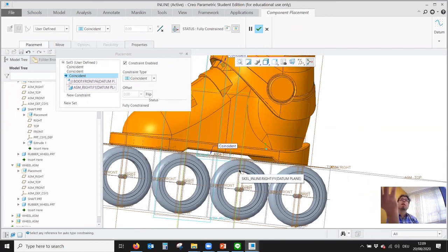So this is already your design. You're designing, but you're not working on the part model, but by changing the skeleton model and thereby changing where's the boot, where the wheels, that's the most important part of the design. You are planning the main dimensions. And then when you're finished with that, you start modeling the new part. And you will put the new part into the assembly and just put in the features that you need. And this is your assignment.